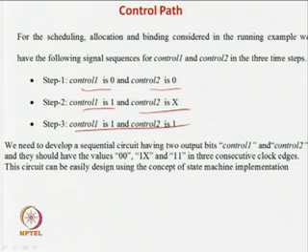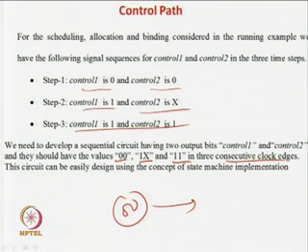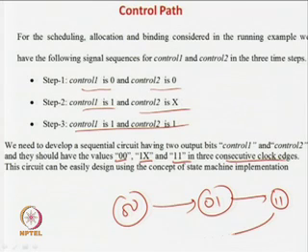So, you now have to generate a sequence with values 0 0, 1 x and 1 1 in 3 consecutive clock cycles. That can be very easily generated by a finite state machine, with output state 0 0, state 0 1 and state 1 1, and these are moving back. At each clock pulse you will move around this finite state machine. Initially 0 0, and sorry, it should not be 0 1, it is 1 0 you can take, because the second bit is do not care over here, and the third state is 1 1. So, if you go around this finite state machine at each clock step, you will be able to generate